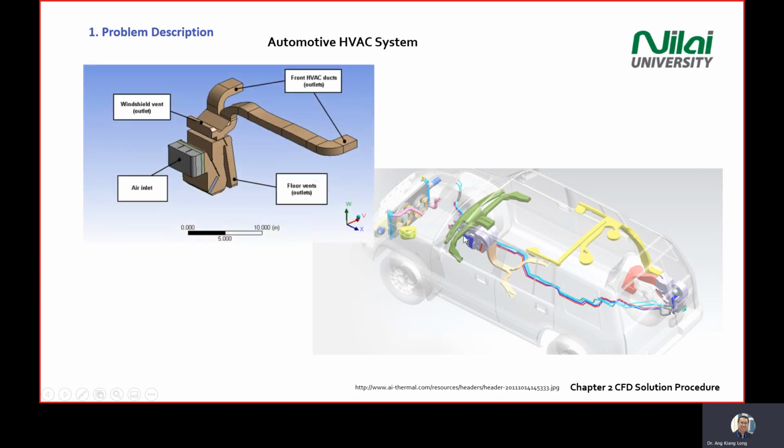Because if you look at this green structure, it is a symmetry object. So to save time in our simulation, we'll do a symmetry simulation, where we will cut this green color aircon in half. And you can see on the left top corner here, we will have the structure of our HVAC system, the duct. So we start with the front.